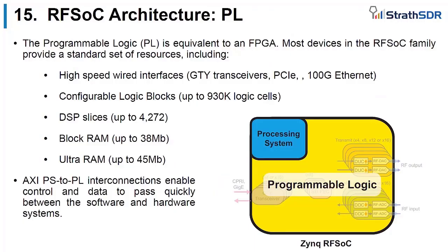In the programmable logic, that's the classic part of an FPGA that we've been using for many, many years. Anyone who's been involved in the FPGA signal processing market for the last 10, 15 years will know we didn't always have the processing system, and we certainly didn't have the D-to-A and A-to-D converters. So in the programmable logic, we've got high-speed transceivers, which are very important because we've got to get a lot of data on and off the device. We've got lots of configurable logic blocks, and depending on the device you buy, that will specify the number of logic cells in that particular device.